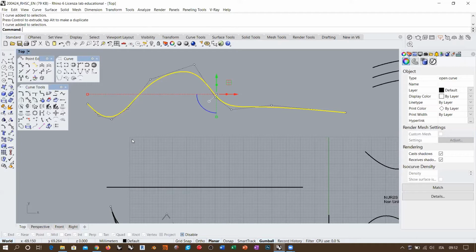You will have smaller spans, with knots which are closer and with less separation, and other parts of the curve where knots are going to be farther apart from each other. And this means that your curve is not a uniform curve. So these are two different commands. Actually, they both rebuild the curve, so they simplify the curve in terms of topology. They change the topology of the curve, but they do this, the first one in a uniform way and the second one in a non-uniform way.